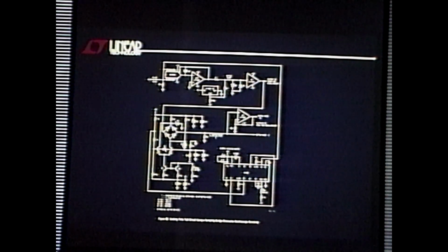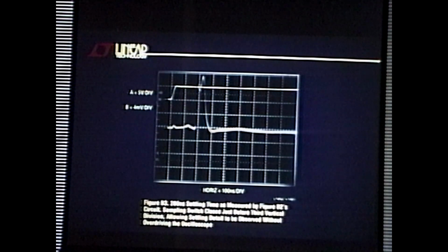The price you always pay for a sampling bridge is you're relying on the DC matching of the diodes. So what you get in a sampling bridge is very, very good AC switching performance with regards to parasitic charge ending up as waveform artifacts out here. What you give up is it's hard to make a good one at DC. So what do we get? Okay, you build all this junk up, you go through all this stuff to get this picture.